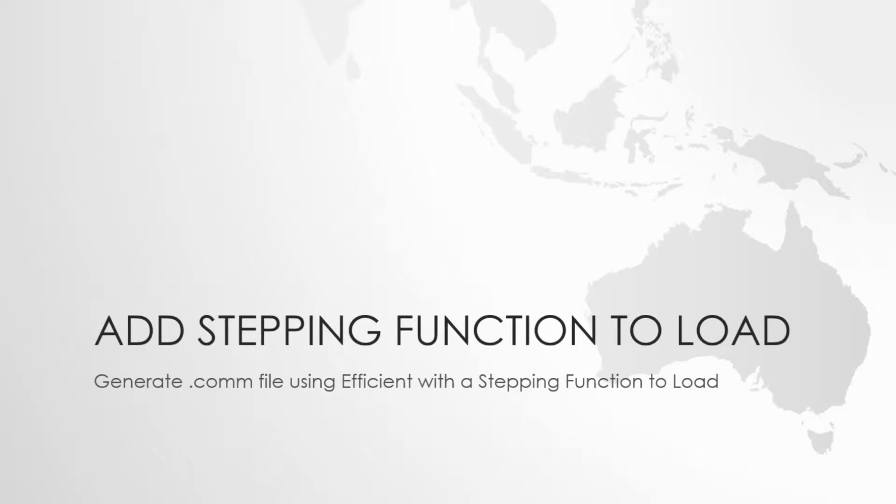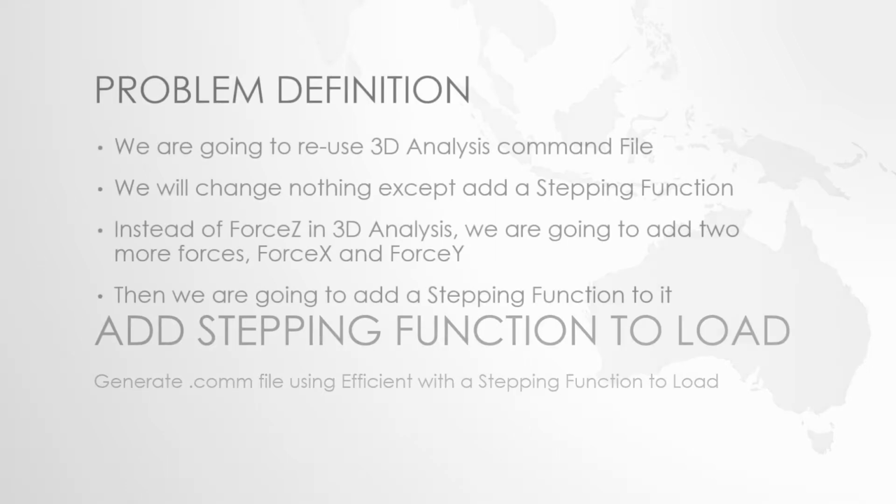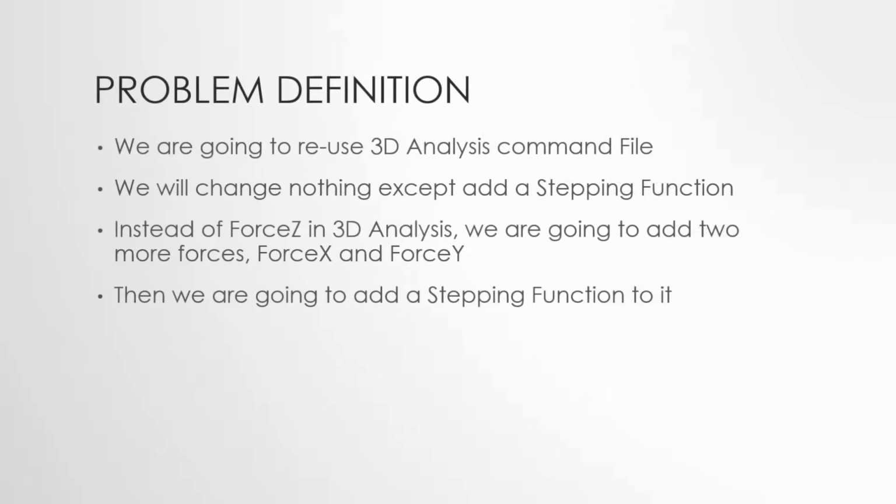In this video, we will look at how to add a stepping function to the load. We are going to reuse the existing 3D analysis command file that we generated previously. We'll change nothing except add a stepping function to the loads.